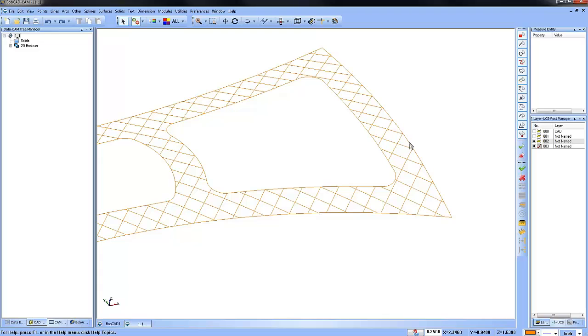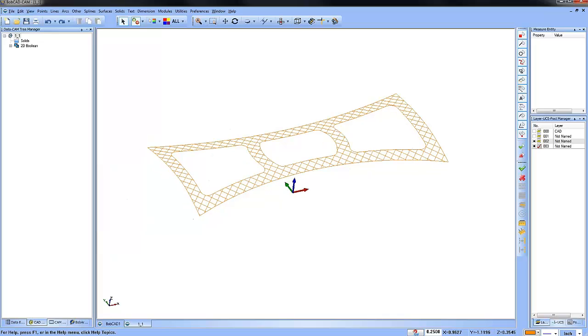When you clean up double entities, the endpoints have to match up. I'm not sure exactly what I have going on there, but when I projected it, I got some additional geometry. We would want to pay attention to that because we don't want to have to recut over where we've already cut. So we may need to go and clean that up, but I want to keep going here because I'm running out of time and I have lots more topics to go through.